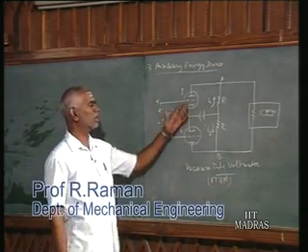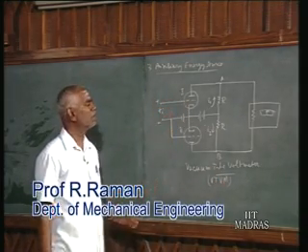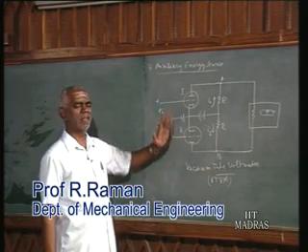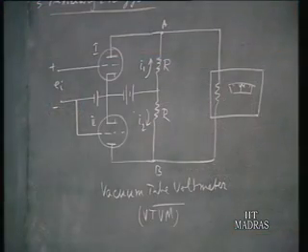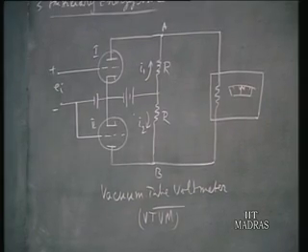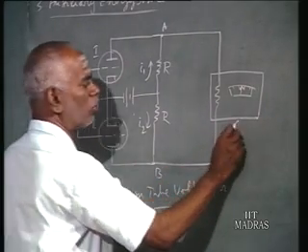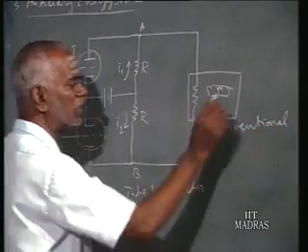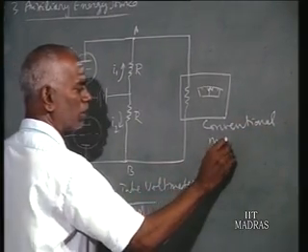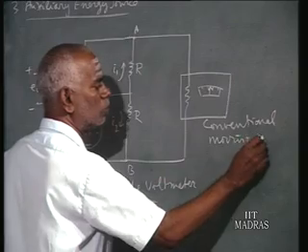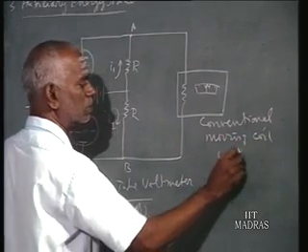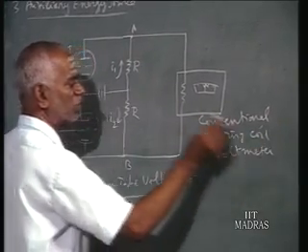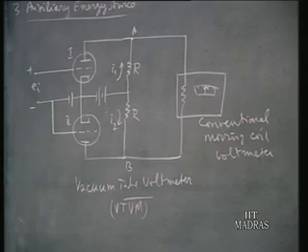Nowadays we have equivalent transistor and solid state circuits, but the same principle is used there. Hence we are using the tube circuit to explain the functioning of a VTVM. Here you will find this is a conventional moving coil voltmeter, which will draw energy from the medium of measurement if we connect it directly there.